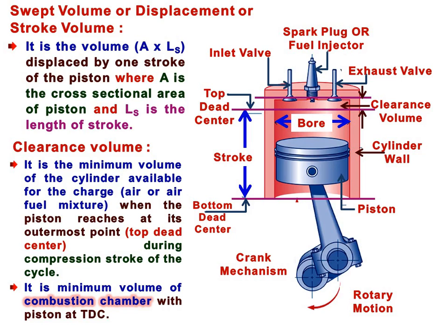At the time when the piston reaches the top dead center in the compression stroke, in the diesel engine, due to the heat of the compressed air, the injected fuel combusts. In the petrol engine, when the piston reaches the top dead center in the compression stroke, the spark plug produces a spark and ignites the air fuel mixture remaining in the clearance volume space.